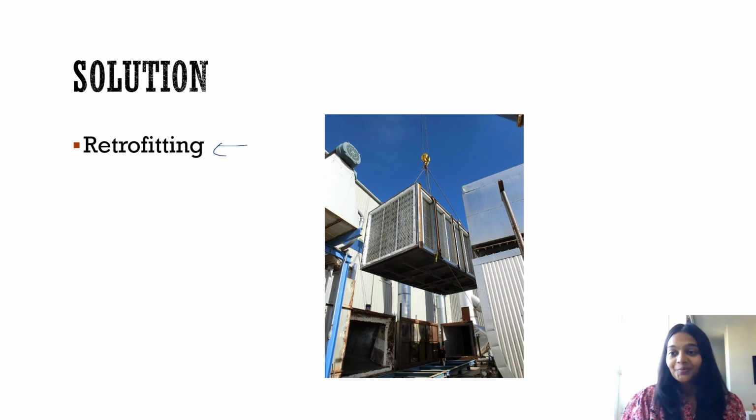I hope you understood the problems that are faced by heat exchanger. It could be either not getting the required temperature, a lot of pressure drop, or contaminated fluid. And the main common problems are fouling, tube vibrations, leakages, and dead zones. So hope by the end of this video, you know what are the industrial solutions and the problems faced by heat exchanger. Thank you.